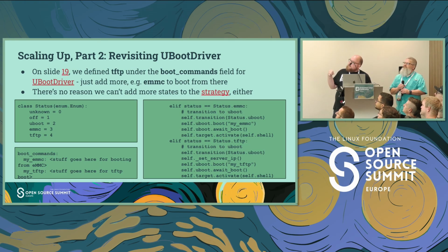It just changes the boot command. So I can switch between these, again, using the Labgrid client command. It's just when I specify -s, instead of saying shell, I can say, or I guess in this case, the status is called TFTP, so I made a typo there. I didn't update it, but I can say -s EMMC or -s TFTP in this case and switch between the 2 boot modes. And in either case, assuming the kernel's good, it's going to come up.